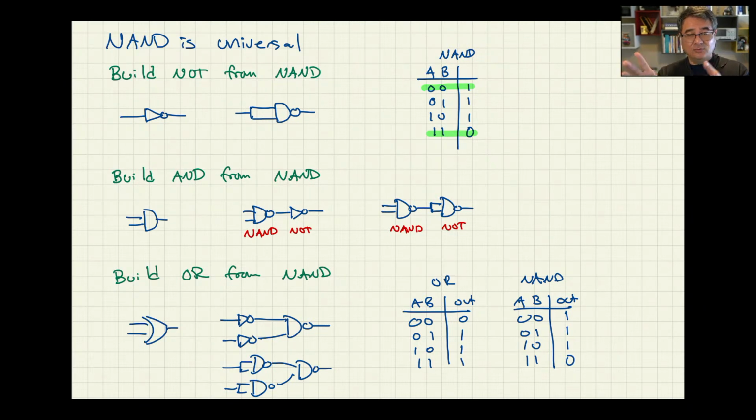So you could actually take one of these logic arrays and build a microprocessor out of it. Once you define how that microprocessor should work, and you can use some of the instructions you saw in Ben Eater's videos, then you can build your own microprocessor out of these logic arrays. And so NANDs are extremely cheap to manufacture. As you saw, they just need two transistors and a couple of resistors, and then that's it. You've got yourself a NAND gate. And that's why they just build them out of NANDs, because they're cheap to manufacture. You just rubber stamp them all over the place on your microprocessor and then just hook them up the way you want, and you can build your processor that way.